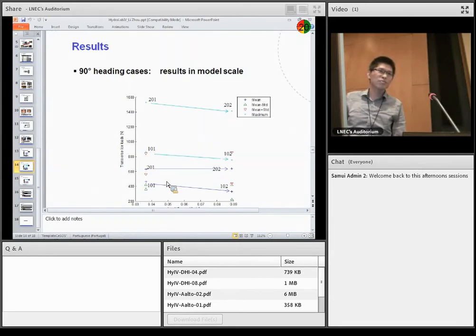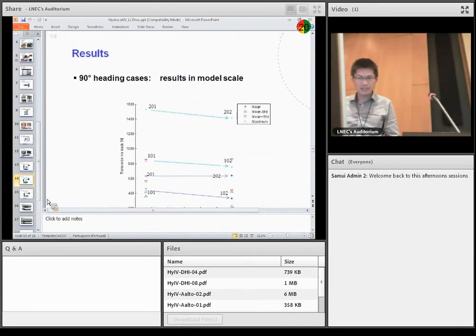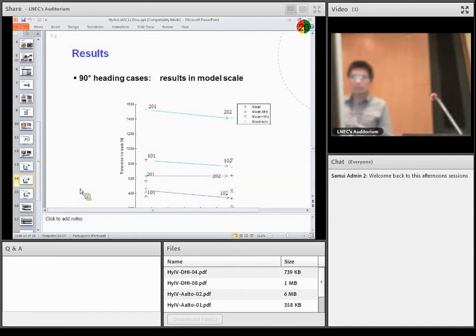I think that would be a presentation of its own. I think Rudik. Well, I can quickly explain that the model ice that we have is fine-grained model ice. We use ethanol to weaken the ice, and there have been full-scale tests compared with model-scale tests in the past that validated that, at least for ice-breaking processes, the ice is scalable. But of course, there are still many areas where the scalability might be questioned.